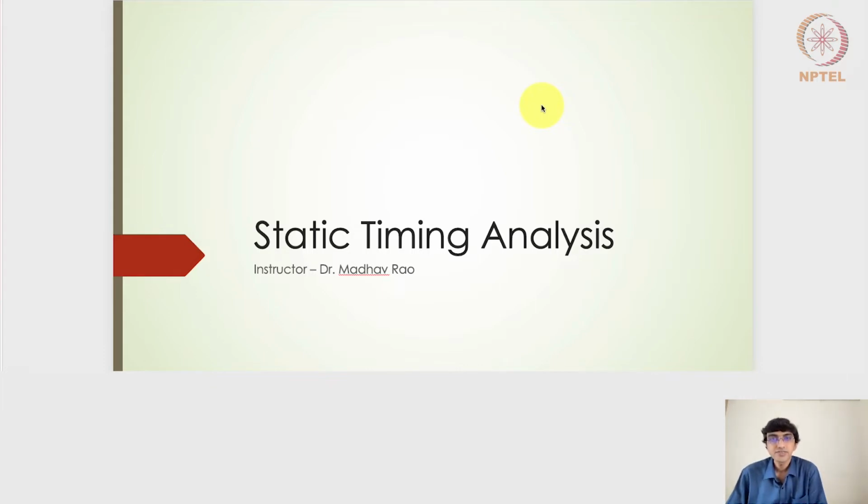In this particular lecture, we will take a look at some examples of combinatorial circuits in between two flops, so that the circuit output is timed. We will use some parameters for the 65 nanometer technology node, the setup timing parameters, and the combinational circuit propagation delay parameters, and then try to design a clock so that it doesn't violate the setup time. In this lecture, we'll also look into hold time failures and proceed further with flip-flop designs.